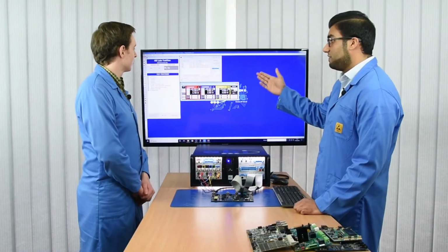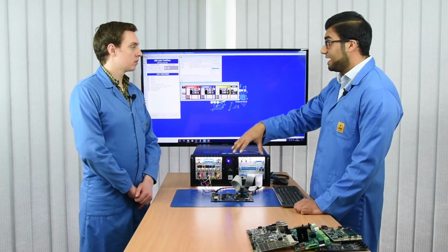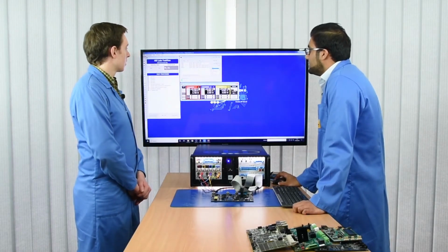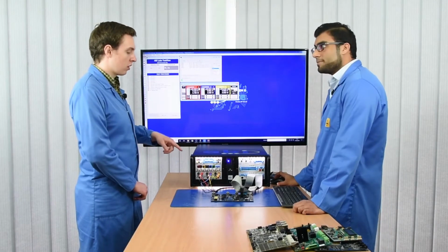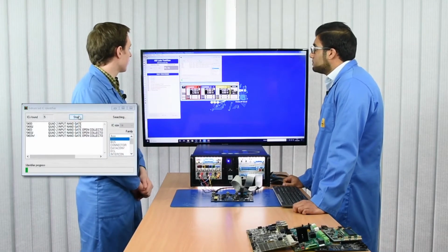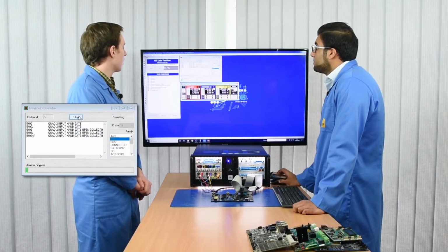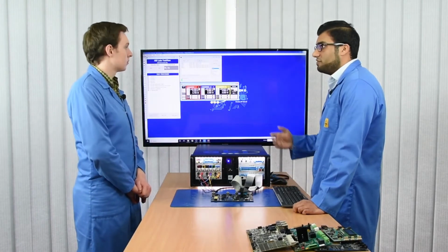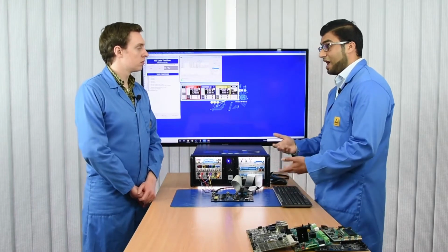Okay, so we can use a 5400 device in the library to test the IC we have in front of us. So what I'm going to do now is click stop. So we'll stop the test here. You can also see that just by running the test, I can get the functionality of this device. We notice that it is a quad 2 input NAND gate, so it's shown us all those. It gives you more information about the device, so you understand how it's meant to work.